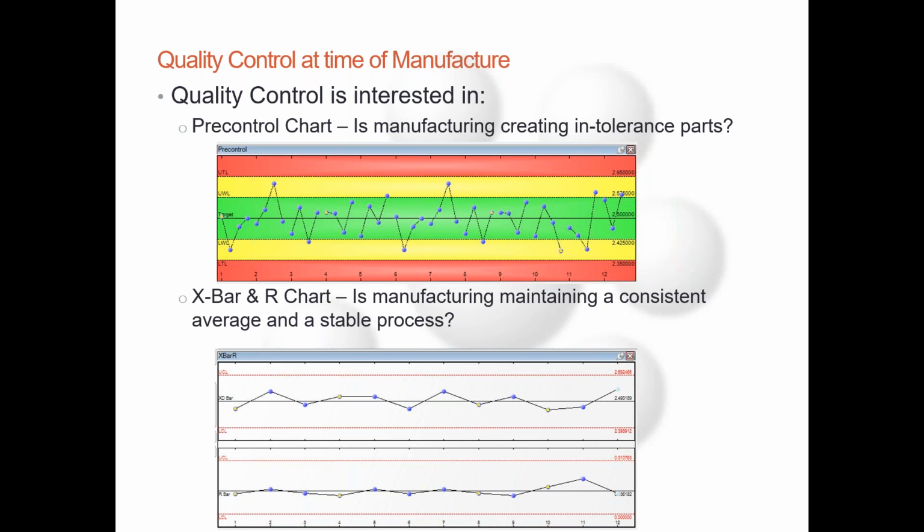So if you're going to do a control chart and you work with a subgroup size of 3, 4, 5, something like that, do all 4 or 5 points in a row just to see how it works. After that, it just becomes a laborious exercise in calculations. And you may even find somebody that will have an online system that will let you try it for 30 days for free or something like that.